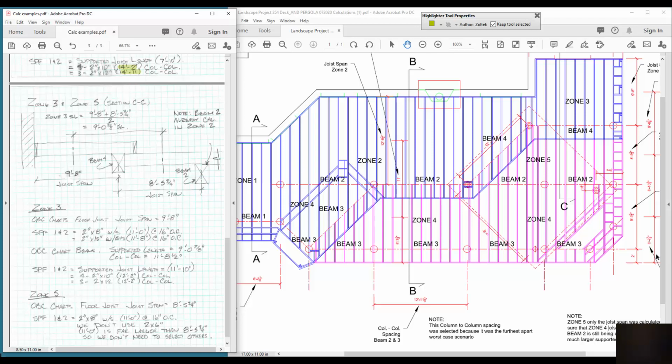Now there's actually a third beam out here, so I've only shown beam 4 and beam 2. There's beam 4 and beam 2. But this purple part of the deck, or magenta color, actually is supported on beam 3 as well. So if I were to colorize this to help us visualize what we have, this part of the deck is our upper deck, and we've drawn this already once or twice. And then the lower deck is the magenta colored one, and that one keeps going. And I've only shown it as a variable that ends right there, but it keeps going and is supported on a second beam.